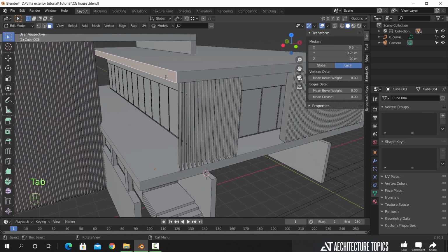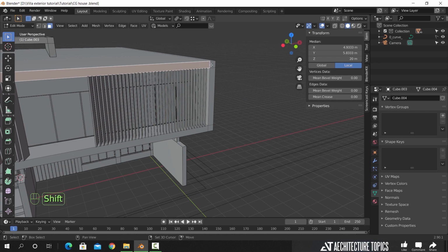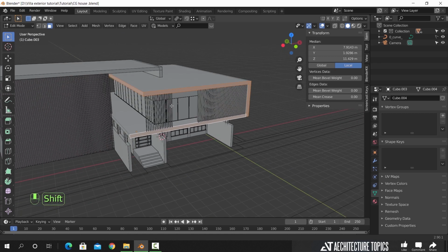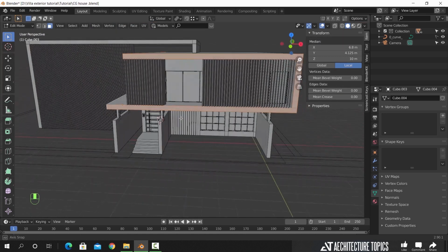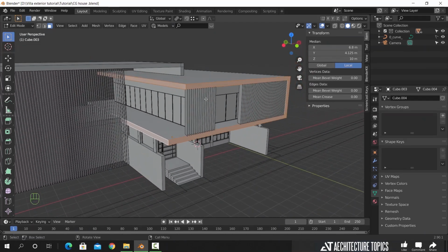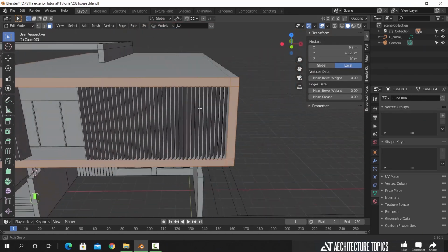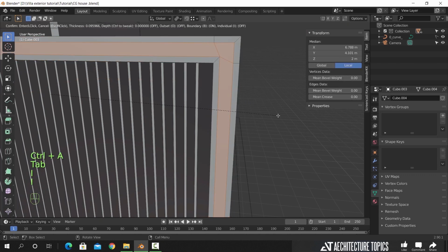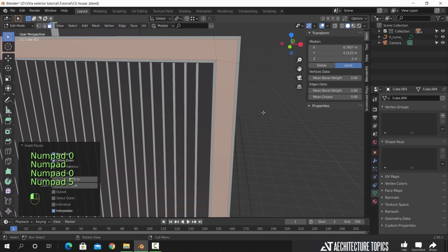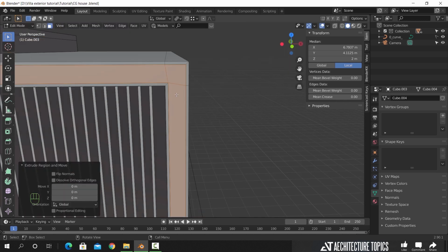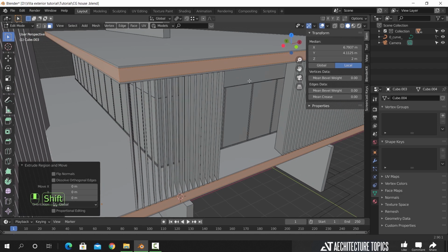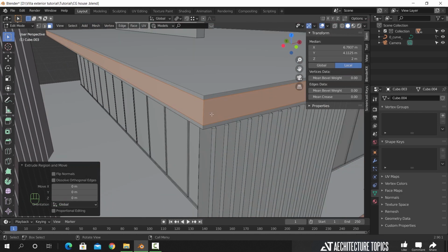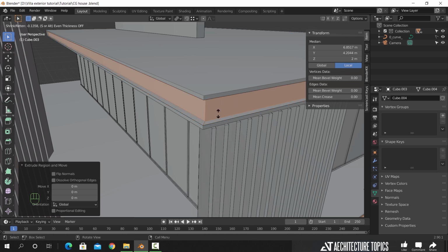In the render as you saw, the floors are separated by two materials, white and black ones, and the white one has some depth in it to inside. So to make that, I will select those faces, apply the scale in object mode, and inset them to inside by 5 centimeters. The resulted edges here are not straight, but it won't matter, so leave them as is. After that, hit extrude along normal to add some depth to the highlighted faces.